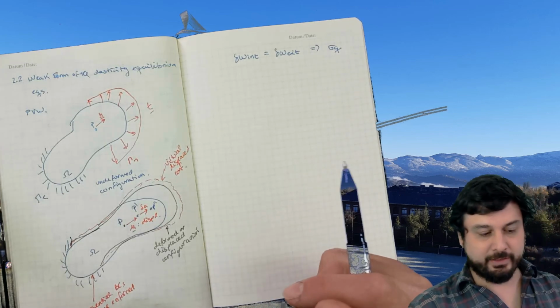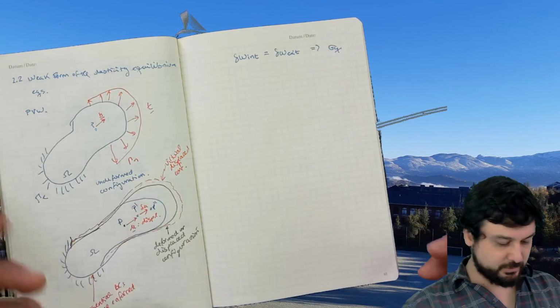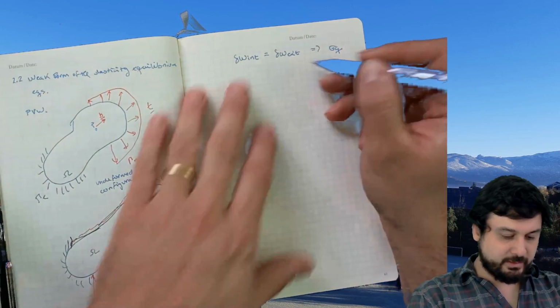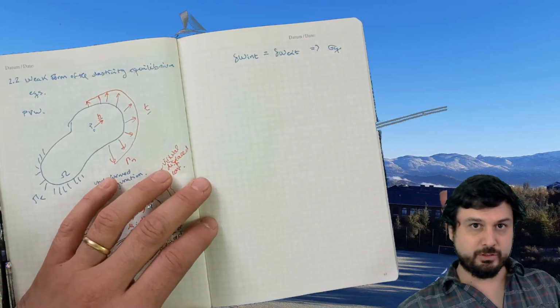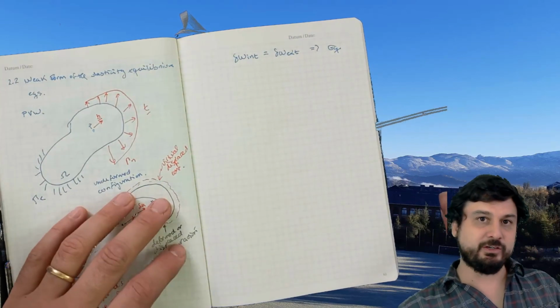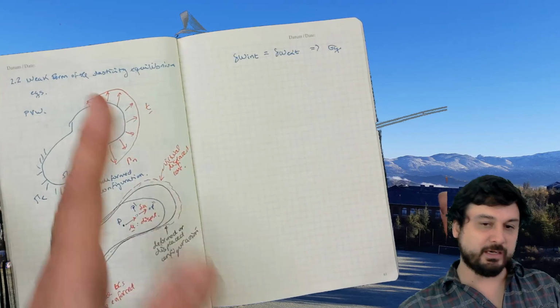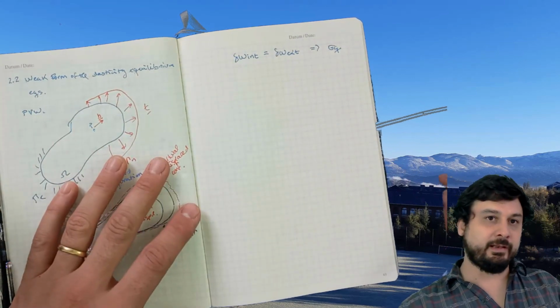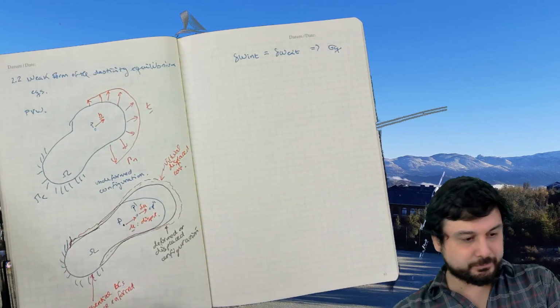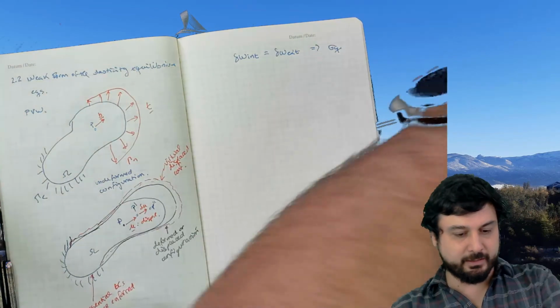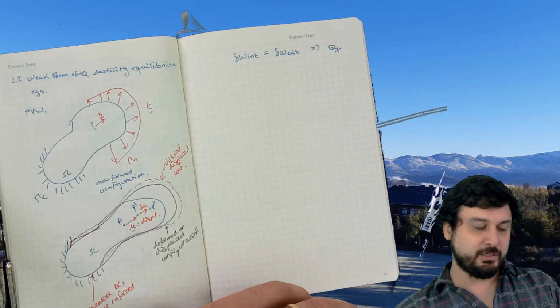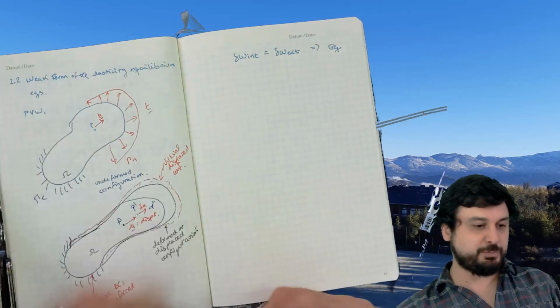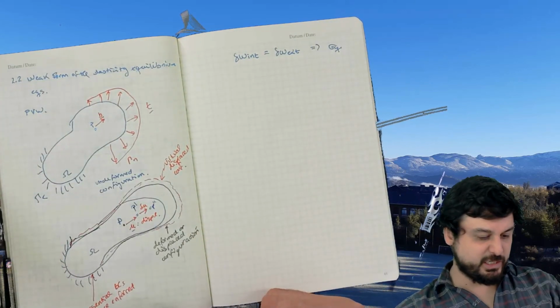Remember I said that the strong form statement is going to lead us to the weak form. The strong form statement is you go at every point inside your domain and you compute that gradient, and if the gradient of the stress field is equal to the body forces, then that's equilibrium at each point. That must be met at each point.